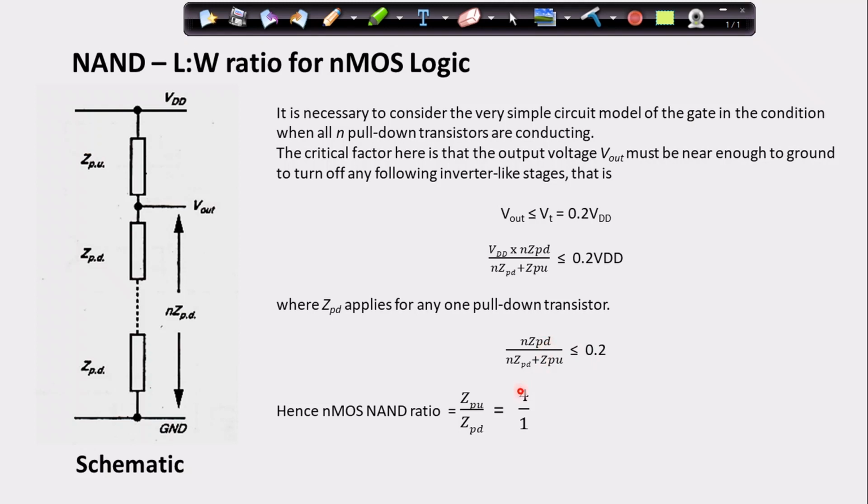So how can I achieve 0.2? Here, as we know for our inverter, the pull down region has been connected in series, that we can observe. If you take the 1:1 ratio, you can observe 1:1. So 1 divided by 1 plus what should be my pull up region so that I can achieve this 0.2? Here 1 divided by 1 plus 4, that means 1 by 5, that will result in 0.2. This value 0.2 I can achieve when I get this particular value.